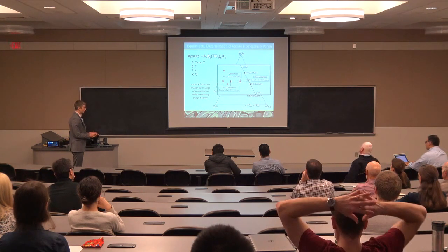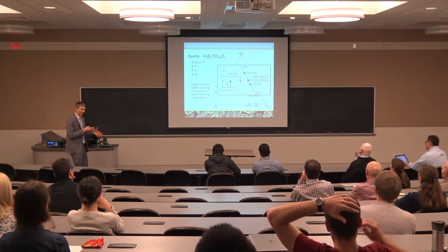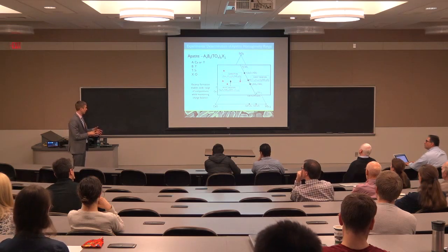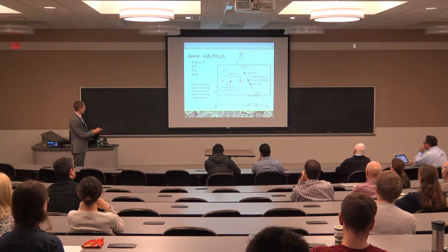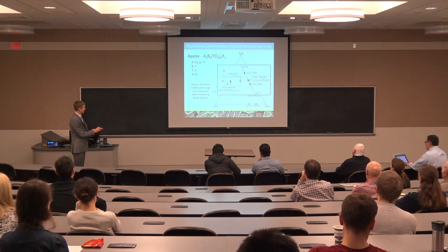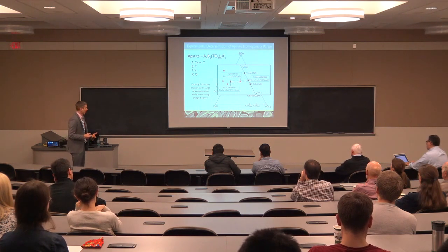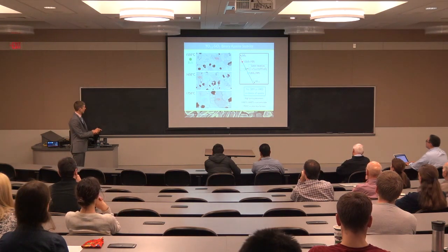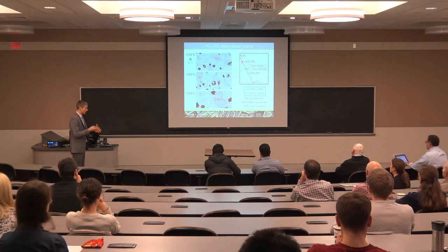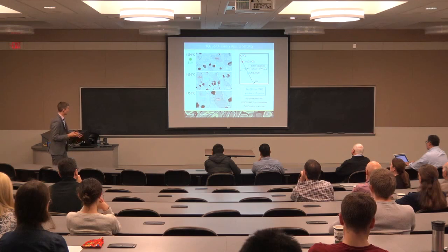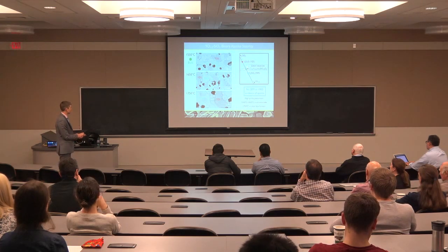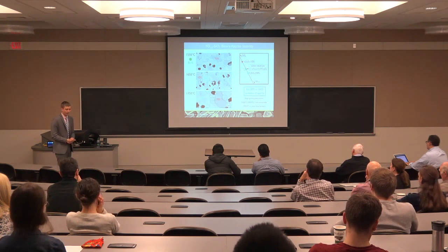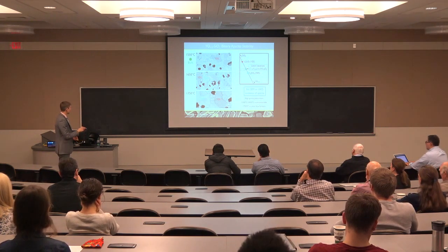And so if we map our understanding of the potential crystallographically allowed stability range onto the phase diagram, we imagine that the apatite phase might sit somewhere in this range. And the next step is to determine where the limits actually are. So if we start by making a composition, just wet synthesis to prepare a specific oxide composition, it sits basically right where the end of the apatite field should sit on this silica yttria binary line. We can anneal it at a range of temperatures.